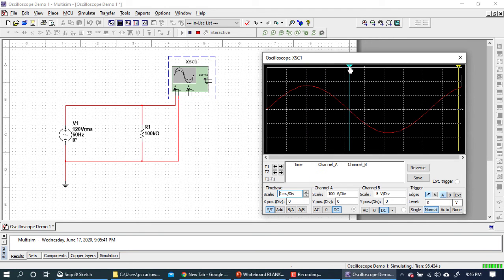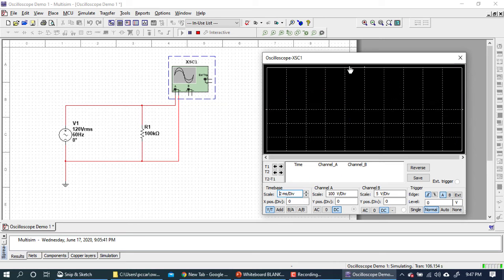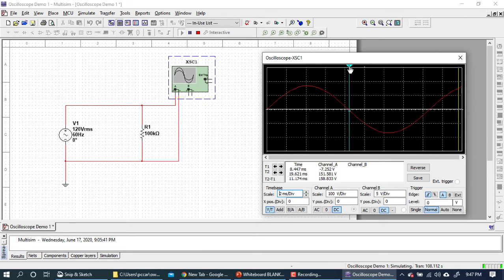What is the voltage here? Well, I can look at it and tell you it's 0. But what's the angular measurement there? Well, the angular measurement halfway of the cycle is 180 degrees. That's halfway around the circle. Well, what's the sine of 180? It's 0. So it's 0 times the maximum voltage, which is what? 0 times 169 volts is 0 volts. So there's no voltage at the 180 degree mark.